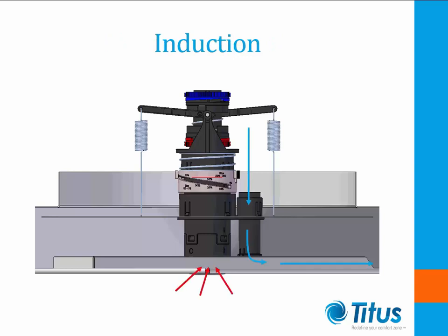Let's talk a little bit about how a mechanism surrounded by supply air measures room air temperature. The Venturi tube, to the right of the central actuator in this drawing, takes supply air at delivery velocity. It throws the air through the induction channel into the space. The velocity of exiting air creates a slight negative pressure that draws air from the conveniently located induction cap, located in the bottom in the center. This room temperature air is forced up into the actuator mechanism to cause the thermal expansion and contraction that creates the motive force of the actuator.